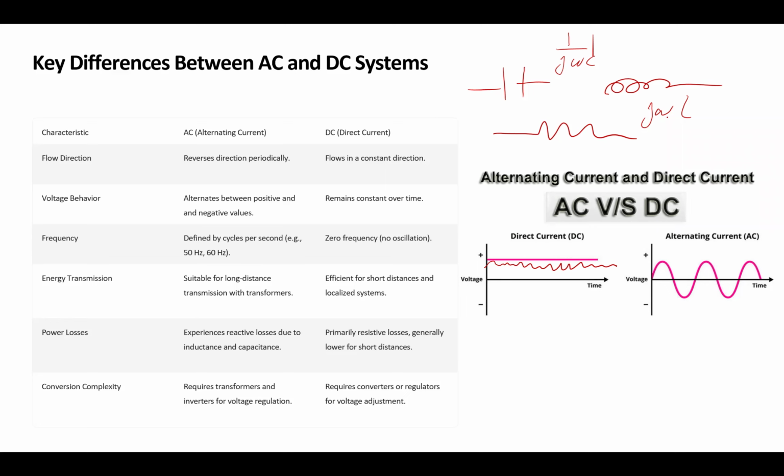If you go over that threshold, they add more cost, like a penalty to your bill. It's not going to happen in a household because a household doesn't have that much L or C effect, or reactive power consumption. But industrial does.